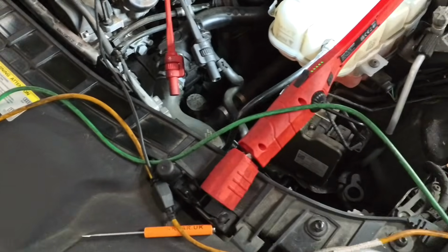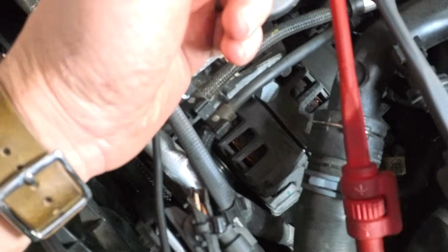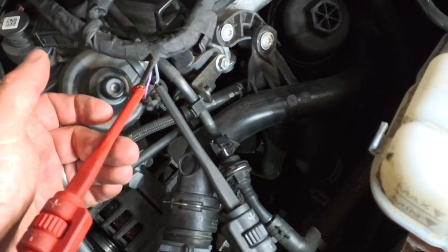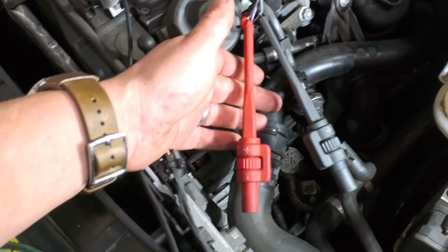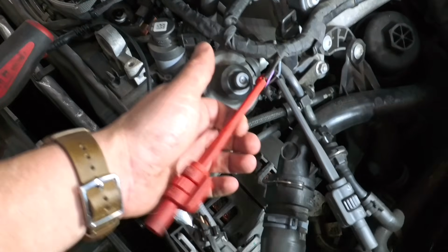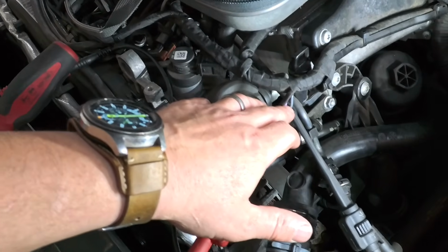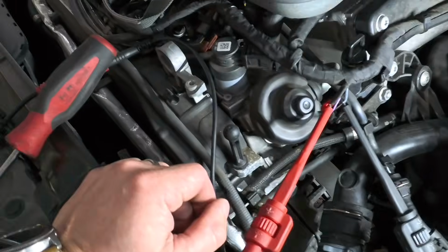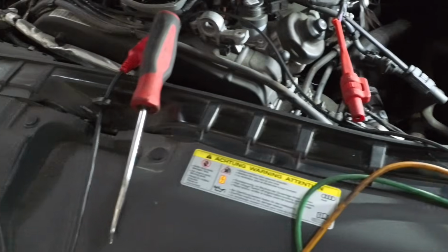So what we've done, because of access issues, is go into the wiring harness a little higher up. Not my favourite way of doing things. I would rather back probe the component directly, but I can't physically get my hand on it very easily, and this is going to be a lot easier and more time effective. Obviously we've probed these wires, but we'll seal them up afterwards so they don't get corrosion in them.